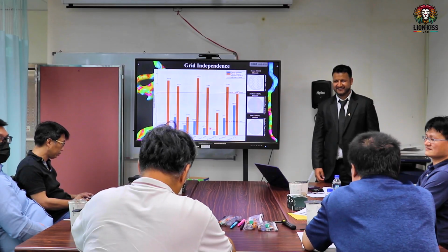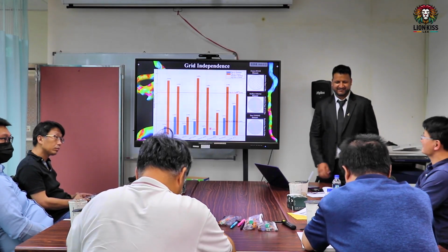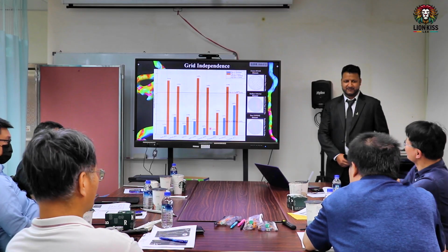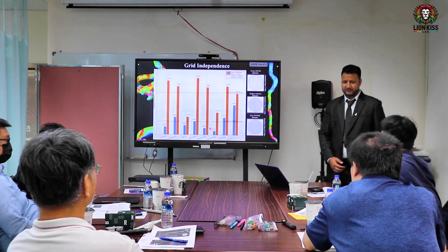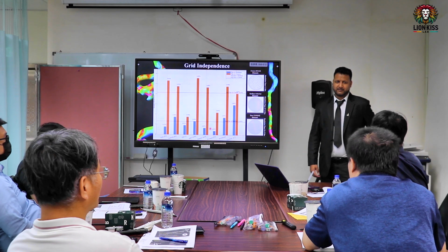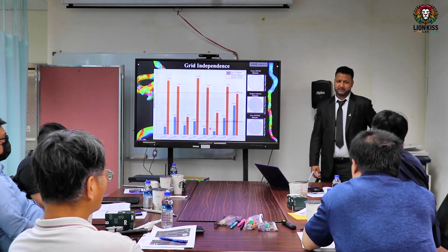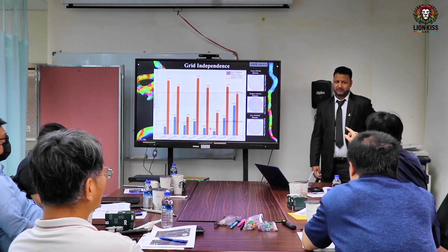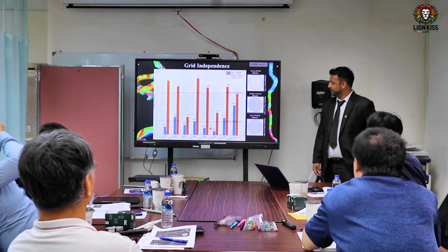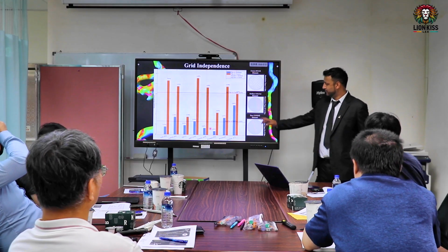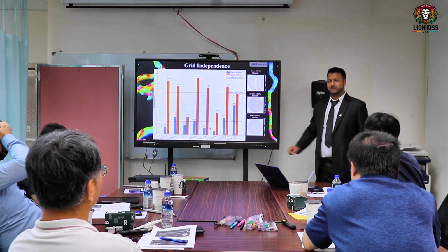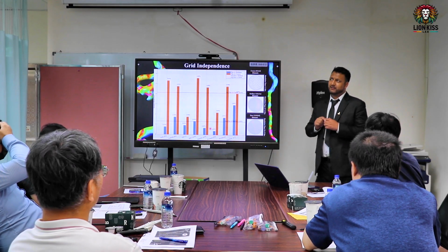Professor Shi will ask a question and comment. Following Professor Hong and Professor Tsai, the Courant number is a crucial factor in numerical stability and convergence. Do you remember how much the Courant number changed across your coarse, medium and fine element mesh sizes?